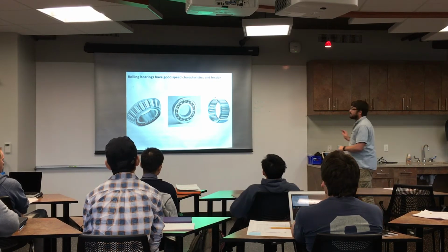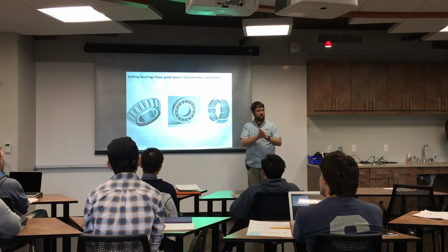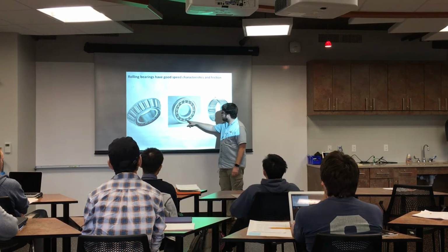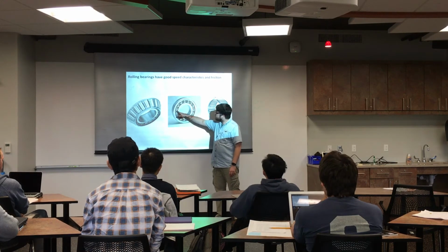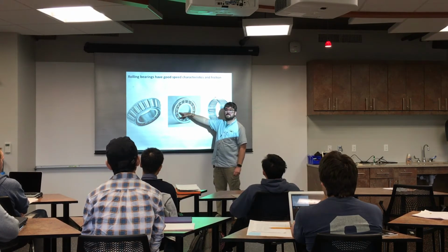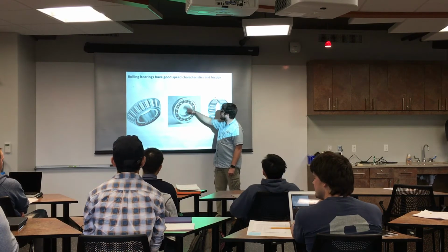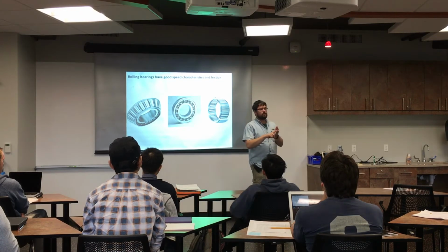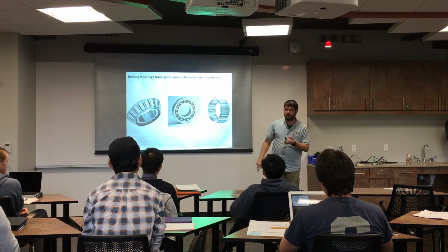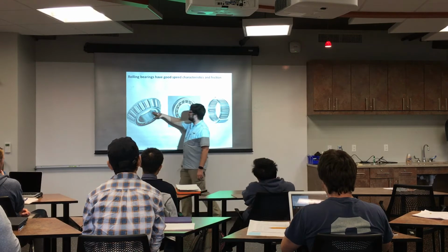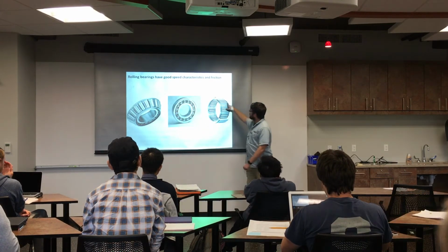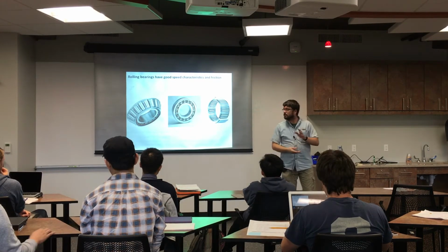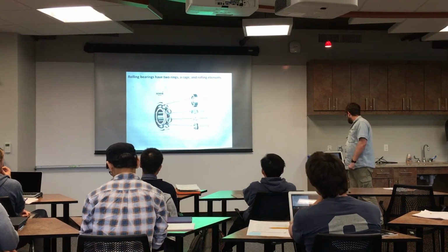If you look inside this, these have a side shield on them to protect from dust and grime and dirt getting in because they go on skateboards. But you would see all of these little hardened steel balls with a separator that holds them fixed apart. That's called the cage, and it rotates. These are called REMs, rolling element bearings, if you're looking them up in a catalog, because they don't have to be ball bearings. They could be cylindrical. They could be these really long, narrow cylinders called needle bearings a lot of times. So a pretty wide variety out there.